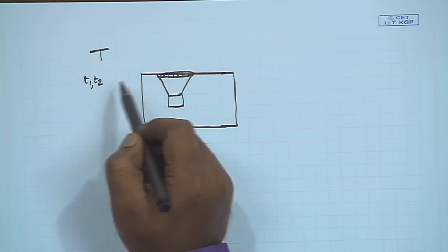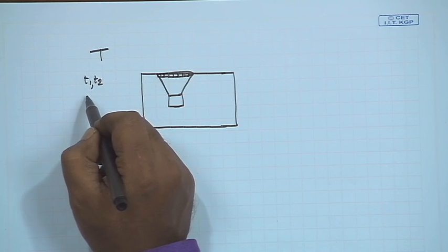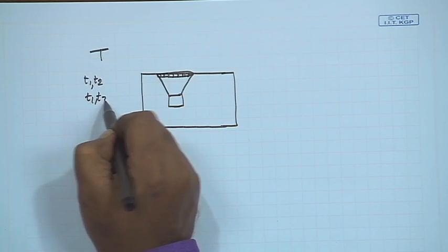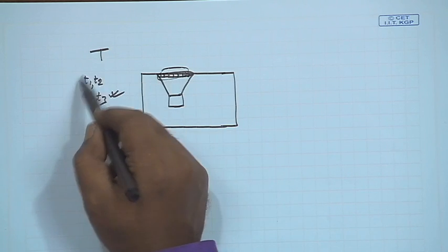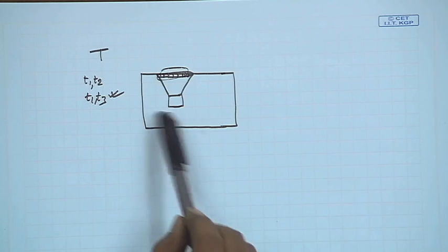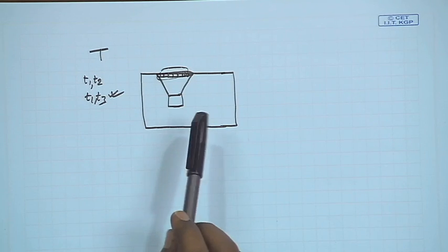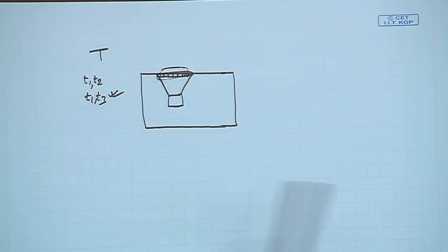If we find that the transitions are less, so instead of applying T1 T2, if I apply T1 T3 and find that transitions in this part are less compared to T1 T2, then it is expected that applying T1 T3 instead of T1 T2 in that sequence, the block in question will consume less power and its activity will reduce.